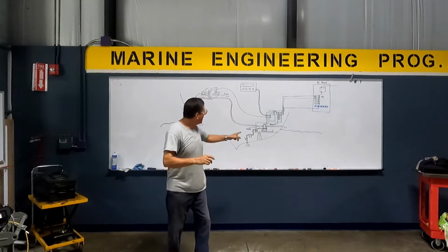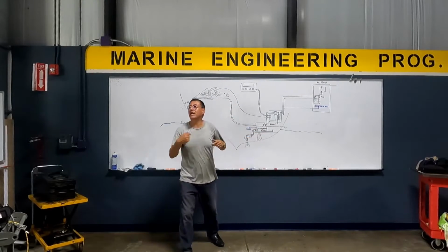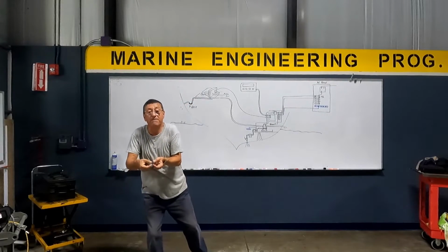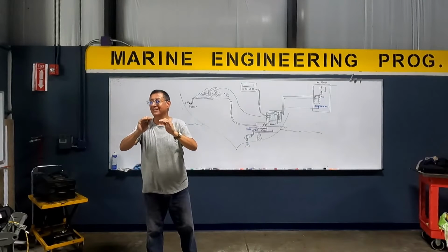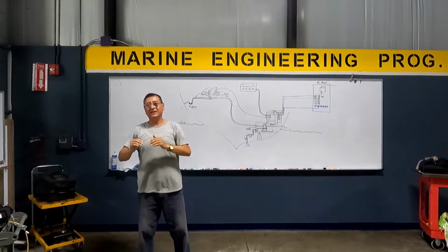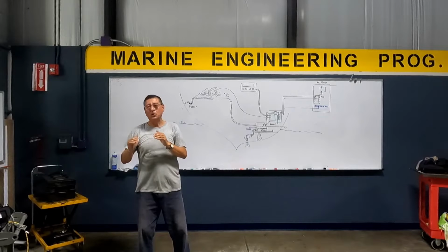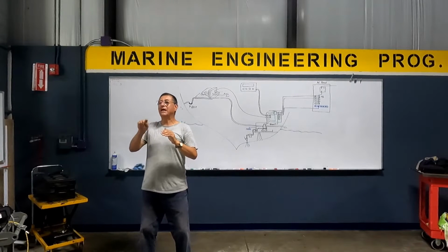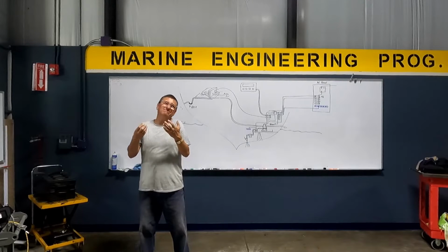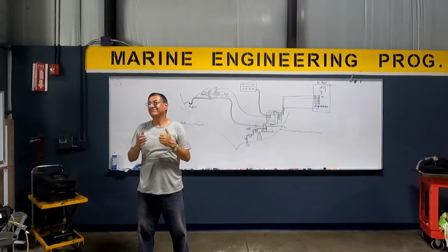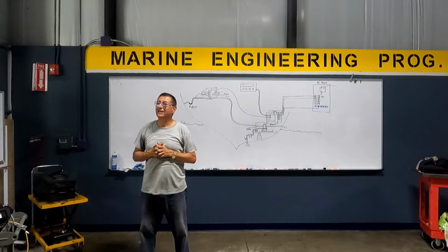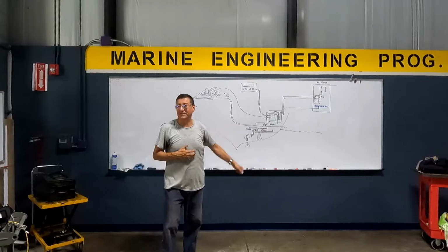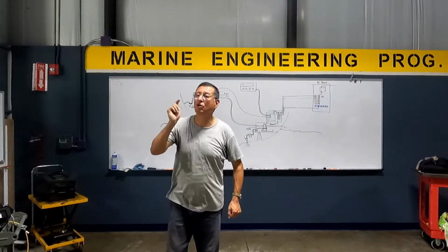Okay. You have a lack of flow of raw water around those pipes. Then the pressure and the temperature of the refrigerant before the expansion valve is higher. After that, the pipes are not frozen, are cold but not frozen. When the ambient air passes through those pipes, you receive no cold air, a little warm. You understand? It's because you have lack of raw water in the condenser coil.